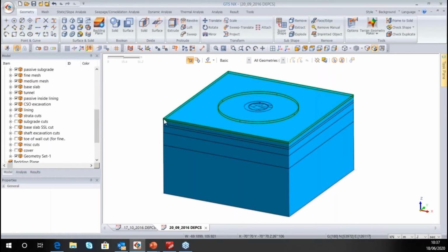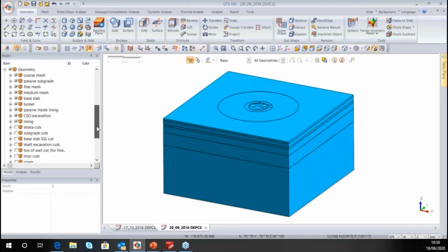So the last thing I just want to discuss on geometry before we mesh: we've auto connected all our geometry, so we end up with all these discrete bits of geometry for meshing. You can get more control of your meshing by seeding your geometry.